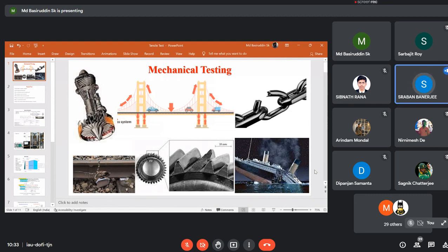Why is it used for these components? Gear, you can say. Not rail line. Rail line actually uses pearlitic steel, but for gear, high-strength steel or HSS, high speed steel, is basically used to ensure high performance and to fabricate that particular component. HSS steel has excellent mechanical properties: the strength and hardness are very high, and the toughness is relatively high.